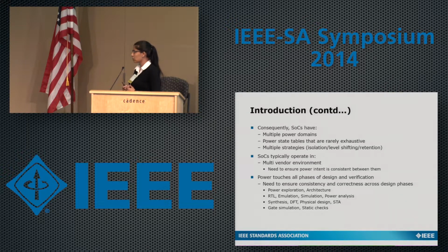The other aspect to consider is that SoCs typically operate in a multi-vendor environment. You might be using a simulation engine from a particular tool vendor, and your synthesis engine might be completely different, and your backend tools, your validation tools, and your emulation platforms could all be from different tool vendors. So there's a huge need for us to make sure that this power intent is consistent between them, and that the modeling and understanding of power stays consistent between the different tools,